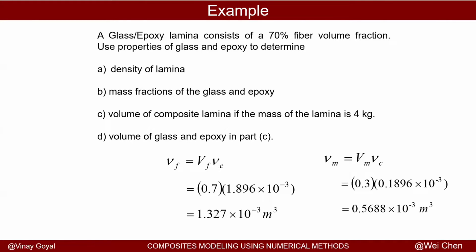So in real applications, composites do contain voids. I invite and encourage you to look at one of the first lectures from the channel, where I give an example of how to treat voids in this type of calculation. There are two ways to calculate voids and the void fraction. A good void fraction in a composite system is 1% or less. That's what you want to shoot for. But void fractions can decrease the strength. If the void fraction is very large, the matrix dominated properties will be impacted, and that level of porosity can be detrimental to the performance of the composite in high performance applications.